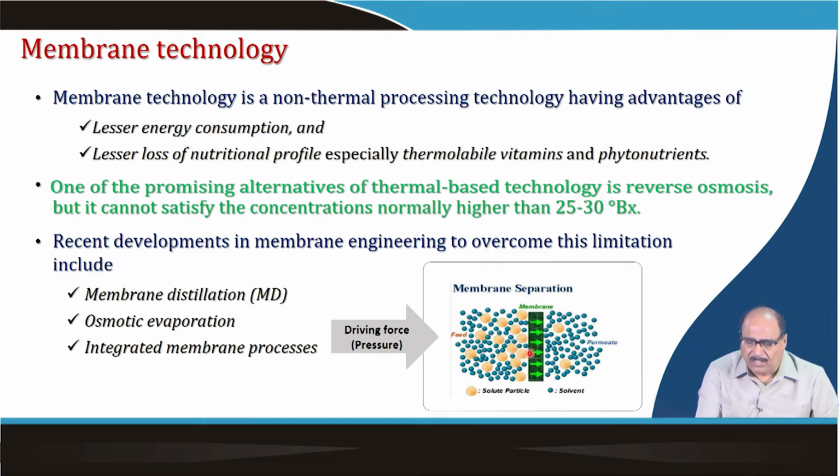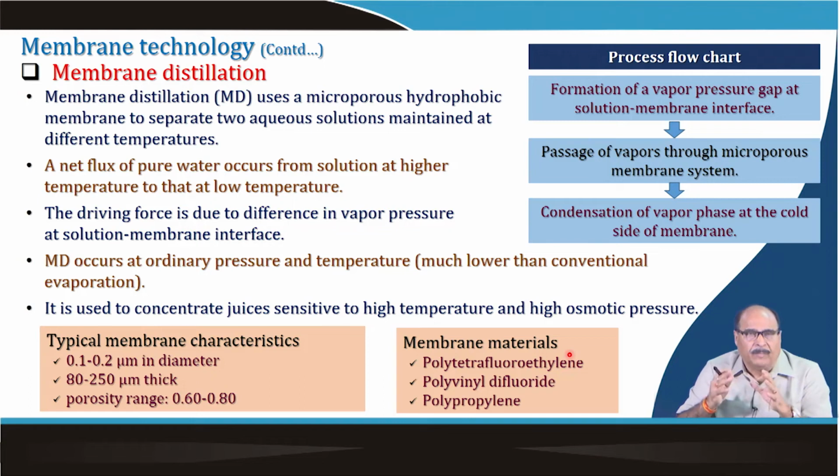The concentrate part you get in the retentate and the water goes out to the permeate. The membrane distillation process uses a microporous hydrophobic membrane to separate two aqueous solutions maintained at different temperatures.